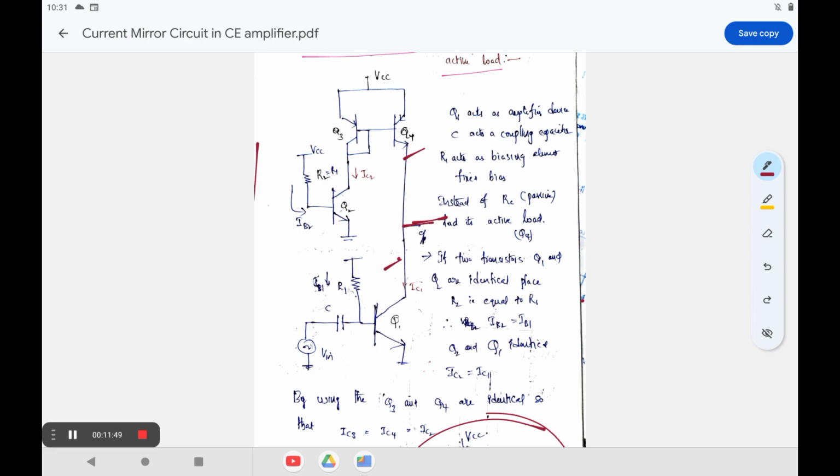The DC biasing is only used for Q point selection. Once the transistor is in the active condition, there is no need to consider the DC analysis. You just think about the AC analysis: how much amplification can be performed by the transistor. That is a very important thing.